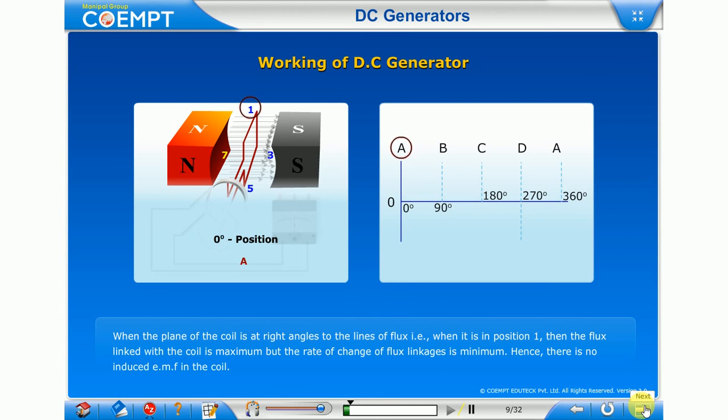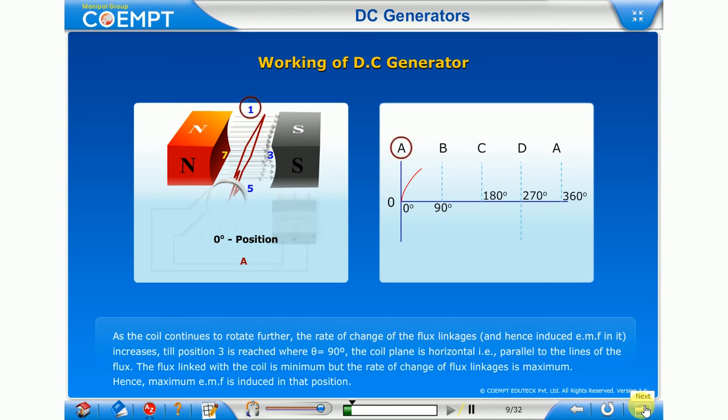When the armature loop rotates in a clockwise direction, from position A to position B, a voltage is induced in the armature loop which causes a current in a direction that deflects a meter to the right. Current flows through the loop, out of the negative brush, through the meter and the load, and back through the positive brush to the loop. Voltage reaches its maximum value at point B. The generated voltage and the current fall to zero at position C.